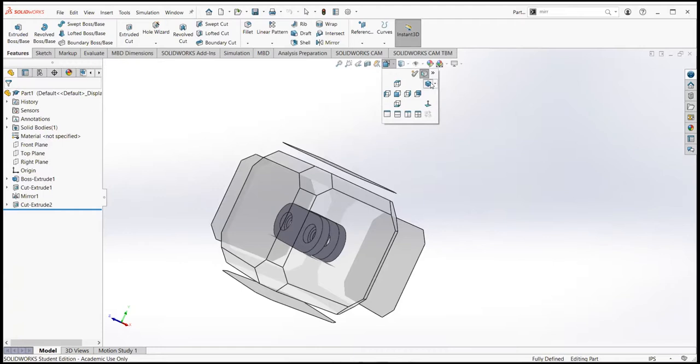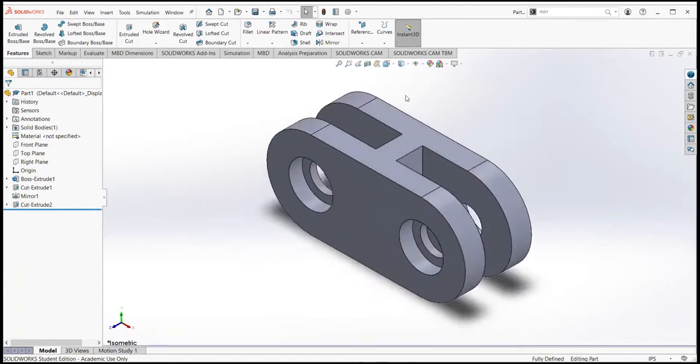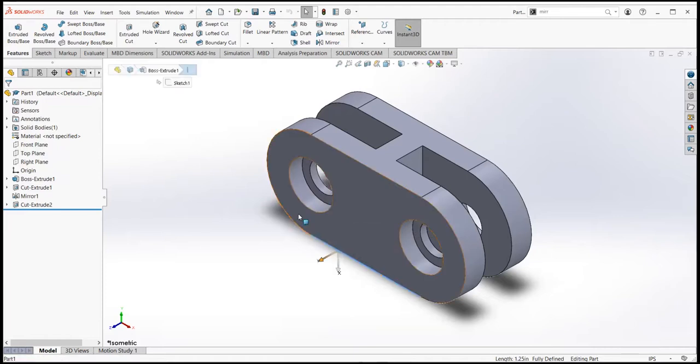Now we want to add finished surfaces for your part. So we want to select all your part except for the circles. Sometimes you'll find it's hard, so make sure you are selecting only the edges, not the surface, because the results will be different. You can do it one time or you can do it once each time.